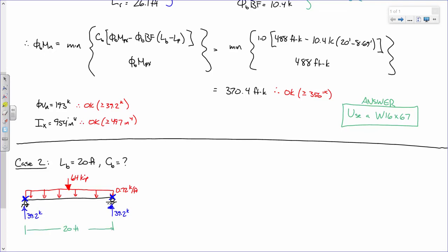On a pin support, how does a brace really change things? A pin can't move anyway, right? You're right, and from our perspective, it really wouldn't. The difference between case 2 and case 4 is that in case 4 there's a brace at midspan. Case 2 is fully unbraced, versus case 4, where it's braced at the ends and at midspan.